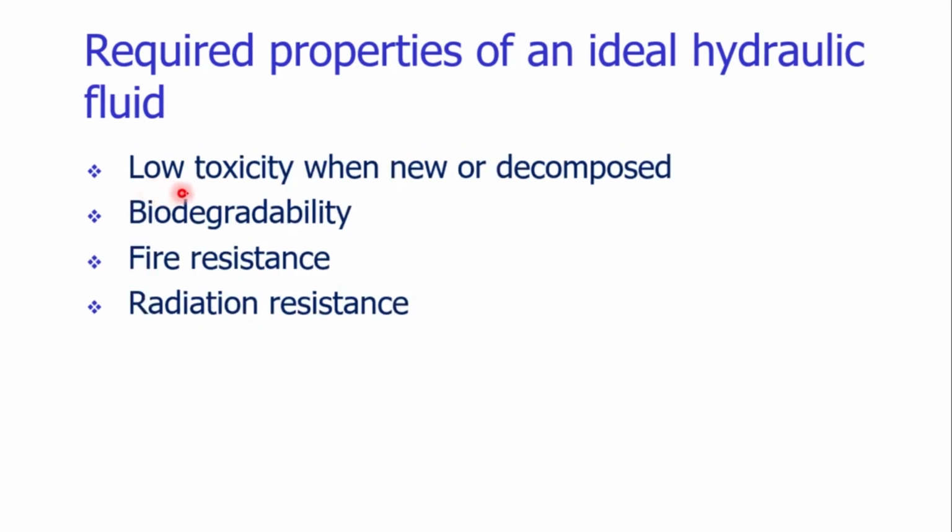The hydraulic fluid should be low toxic. We are using the hydraulic systems in the presence of human beings. The fluid will be handled by human beings. So it should not harm the health of human beings. It should be less toxic. It can be easily decomposed. If it is biodegradable, that would be the best hydraulic fluid. It should have resistance to fire and even radiation resistance as well.